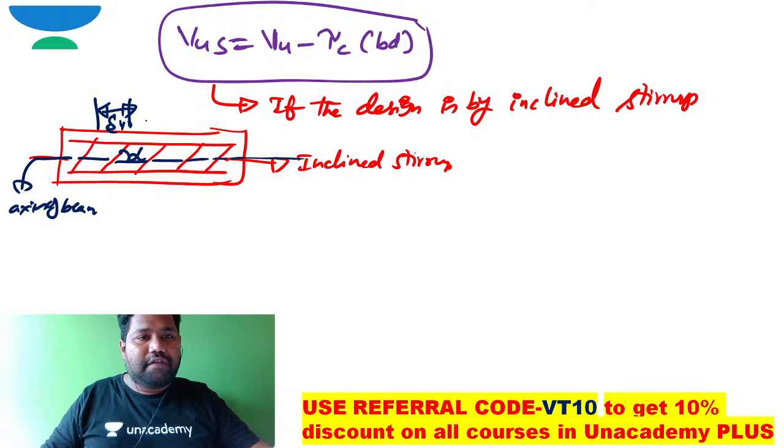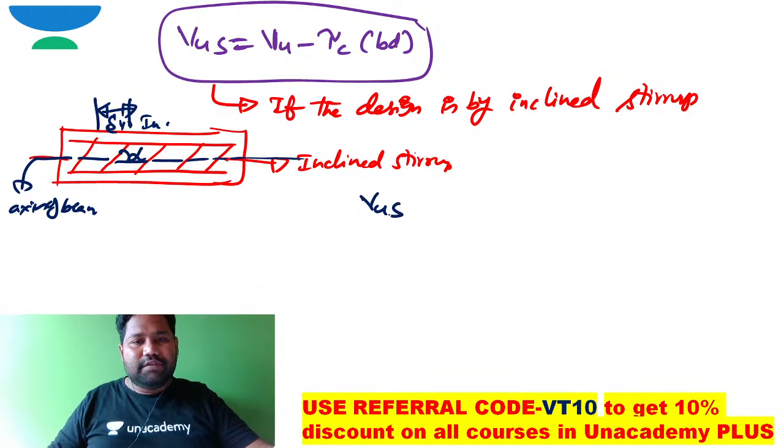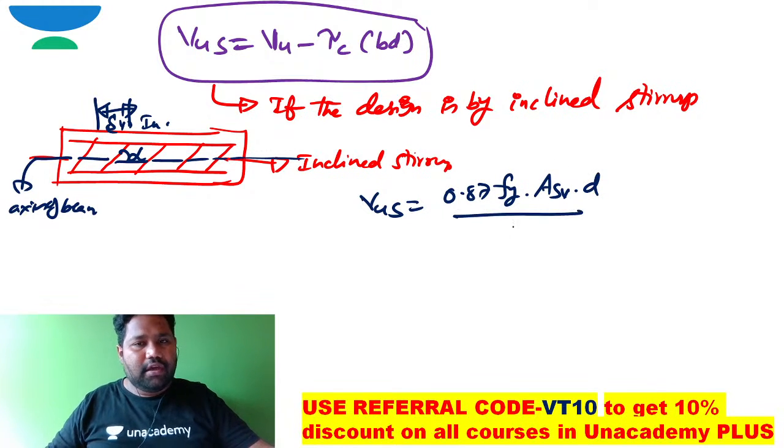For inclined stirrups, I can write Vus is equal to, just as previously for vertical stirrups, the same equation: 0.87 Fy Asv into d by Sv. We will write it as it is. But here the stirrup is making some angle alpha.